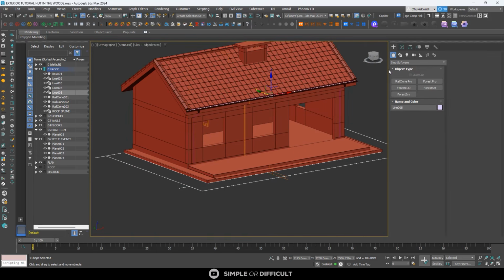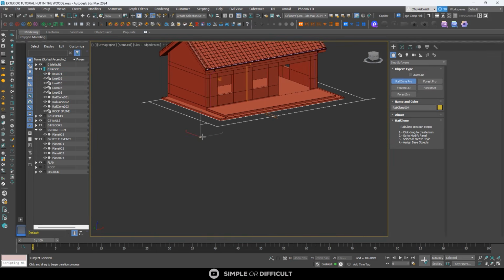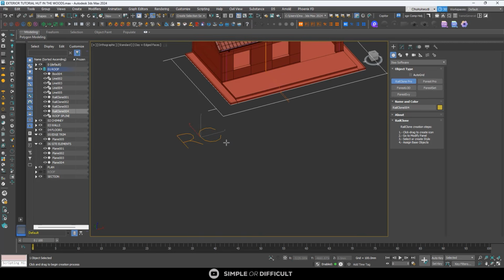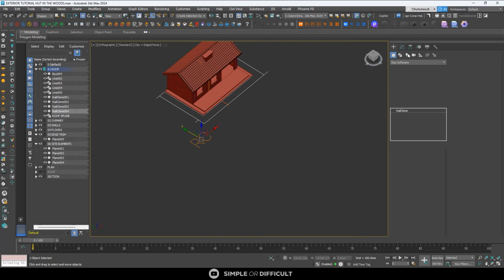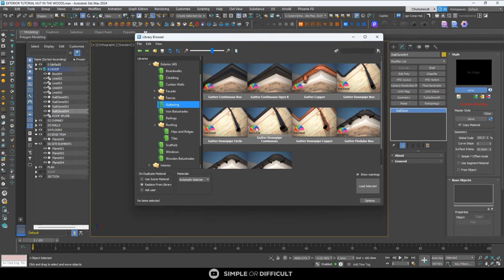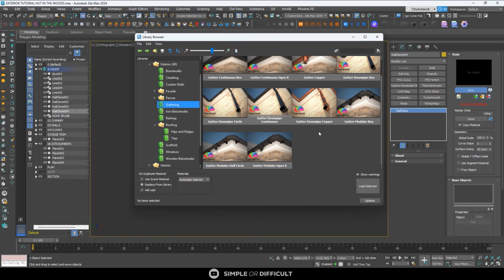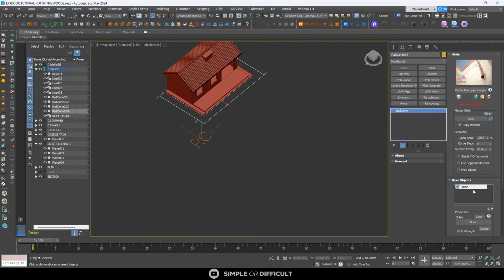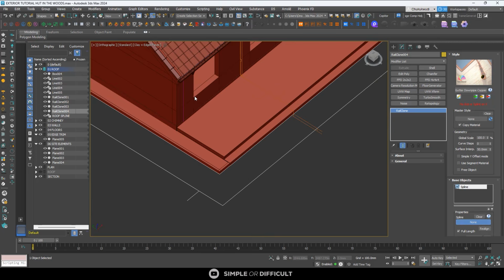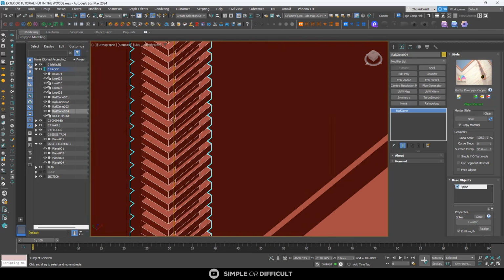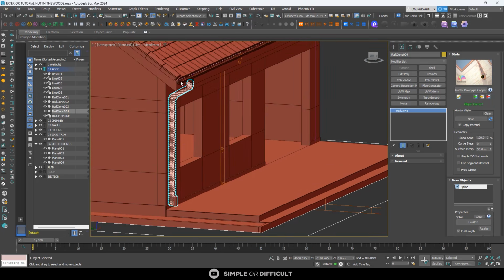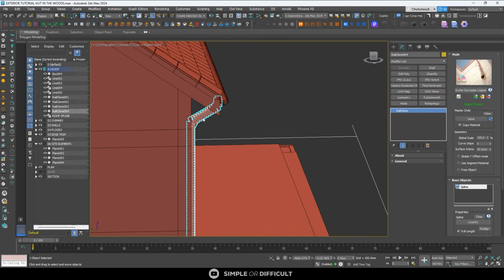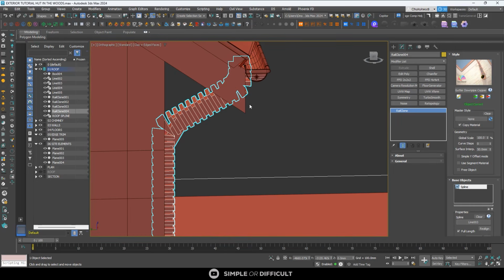To create a down pipe, what are we going to do? Create another RailClone object. So come in here, click on none. You see the pipe that we're having here. So what I need is a round pipe. This one. And then I'm going to load it in. And we're already here. I'm going to click on this and I'm going to select this. When I do that, a lot of things happened. So we're just going to make an adjustment. Wait, I thought I selected the round one.